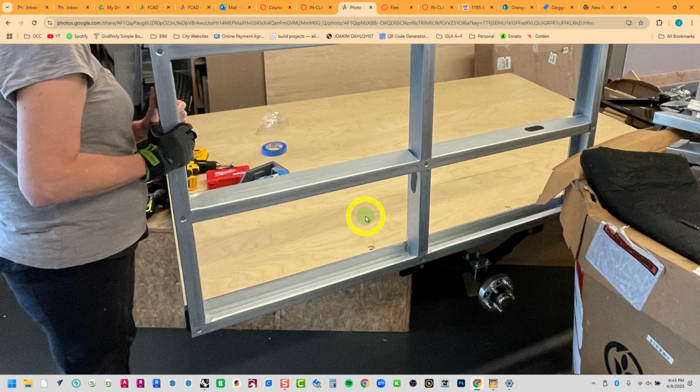One unique thing that we did for this specific project was instead of putting these walls directly on that plywood, we actually mounted it to the side of the frame, which we did because we wanted to fit a queen-size mattress inside, which we did. But the disadvantage of that is that you need some really good steel brackets that mount to the underside of the trailer and then clip on to the bottom side of those walls. And if you think about that, buildings are not built in that way, right? They're not just sitting on little teeny tiny brackets. Walls are usually built right on top of foundation walls or a concrete slab, not some accessory little bracket, right?